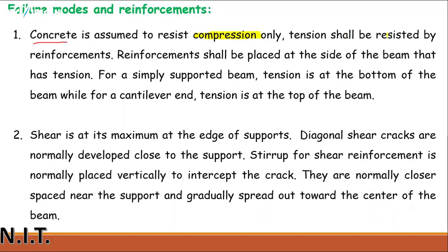Tension shall be resisted by reinforcement. Concrete resists compression and tension is resisted by reinforcement. Reinforcement shall be placed at the side of the beam that has tension.